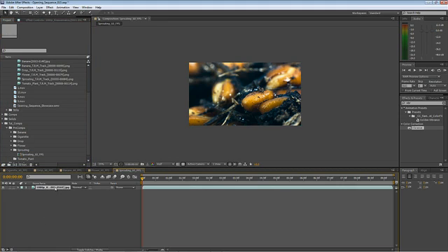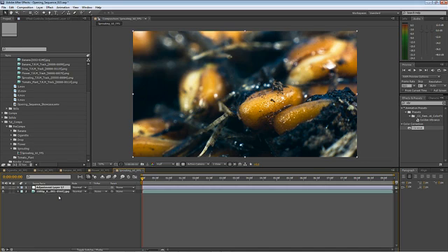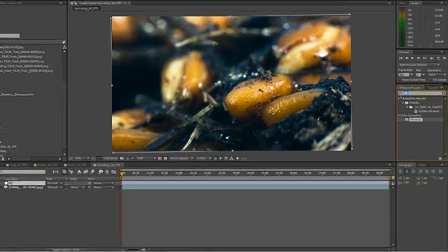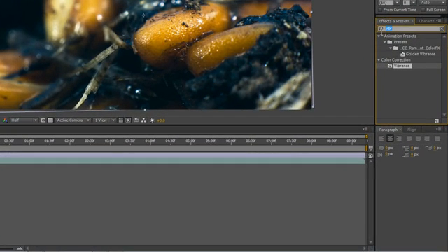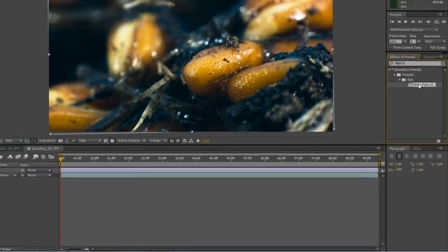And again, from my experience, the HDR toning isn't yielding the result I was aiming for, so I would use just a basic color correction. Ctrl-Alt-Y to make a new adjustment layer, rename it to CC. We'll add, once again, levels, curves, and vibrance, and for those 3 effects I also have a preset called Fast CC.